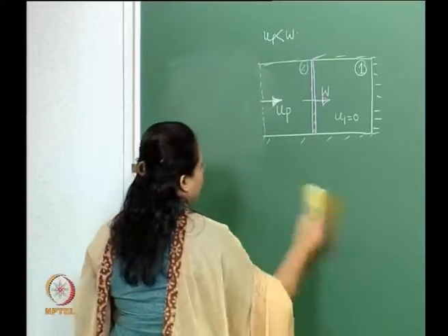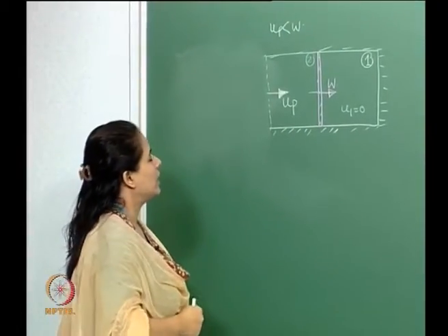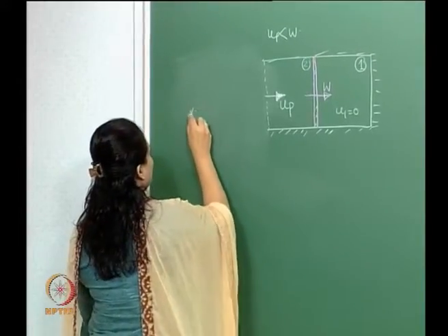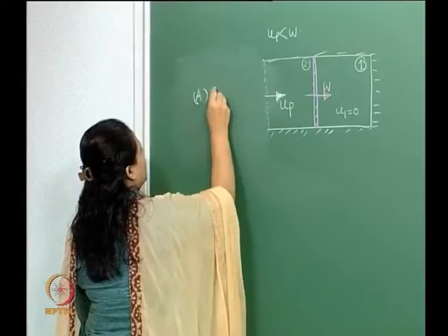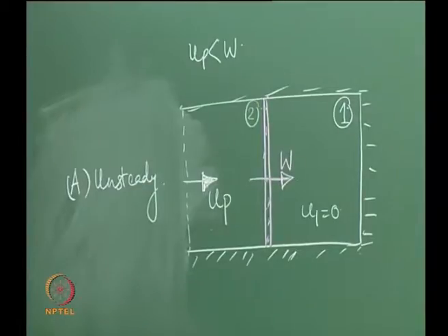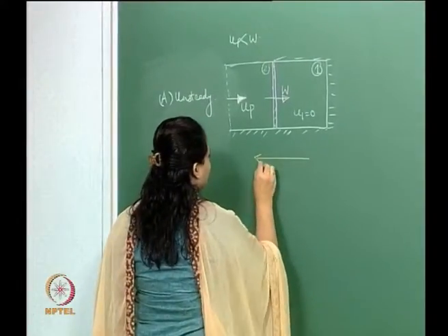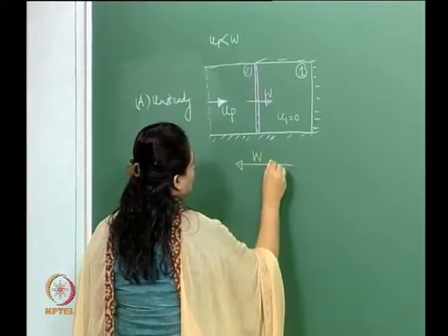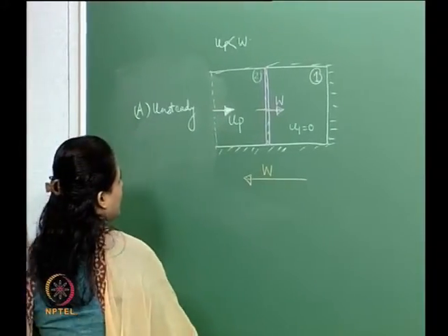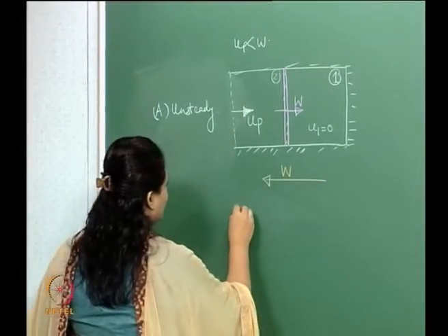So we have a shock which is traveling to its right. This is the unsteady shock wave traveling. Now, if we have to convert this to the steady state case that we're most familiar with, then all we will do is superimpose this flow with a velocity W in this direction. Let's redraw that.